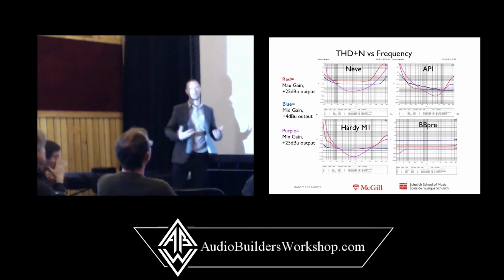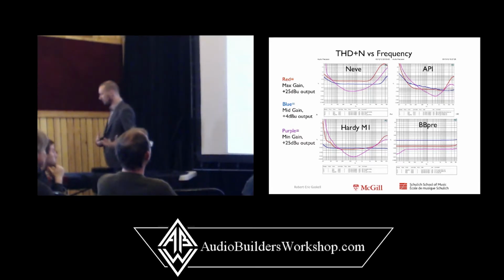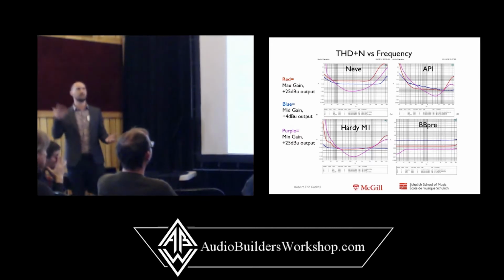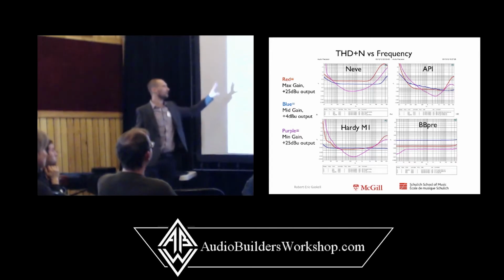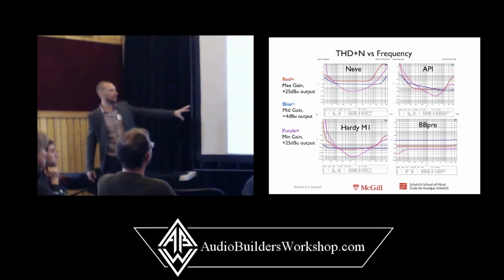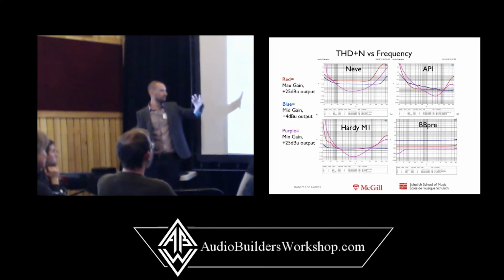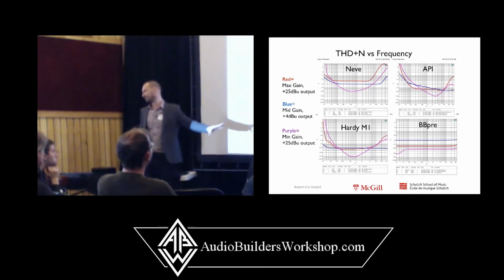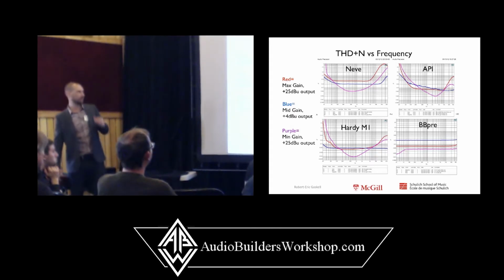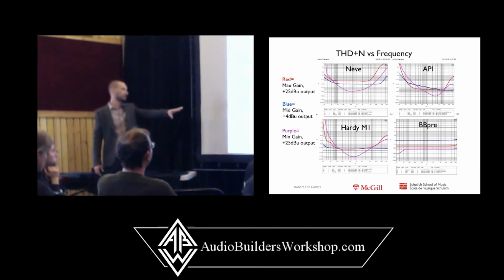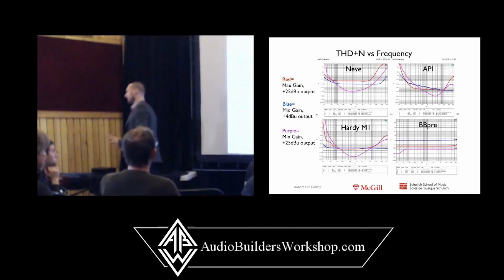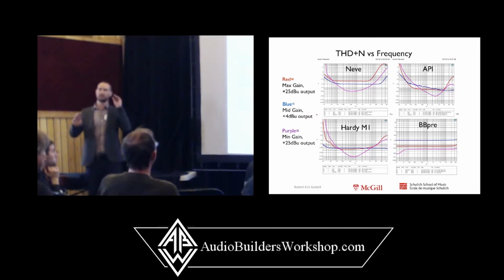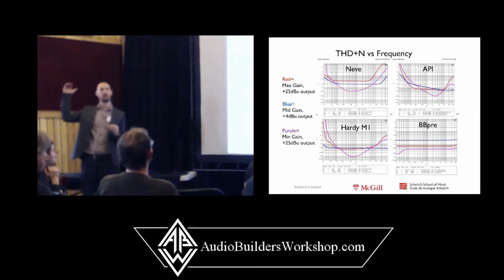So it's possible that one thing that people appreciate about the low frequency distortion created by these transformers is the way that they eliminate, first of all, excess subsonic frequencies that you don't need, tightening up the sound, but also give you this increased sense of low fundamental presence, even if it's not actually there as much, based on the harmonics that it generates. So what you see here are the Neve, API, Hardy, and basically a transformerless integrated circuit instrumentation amplifier mic pre, all compared.